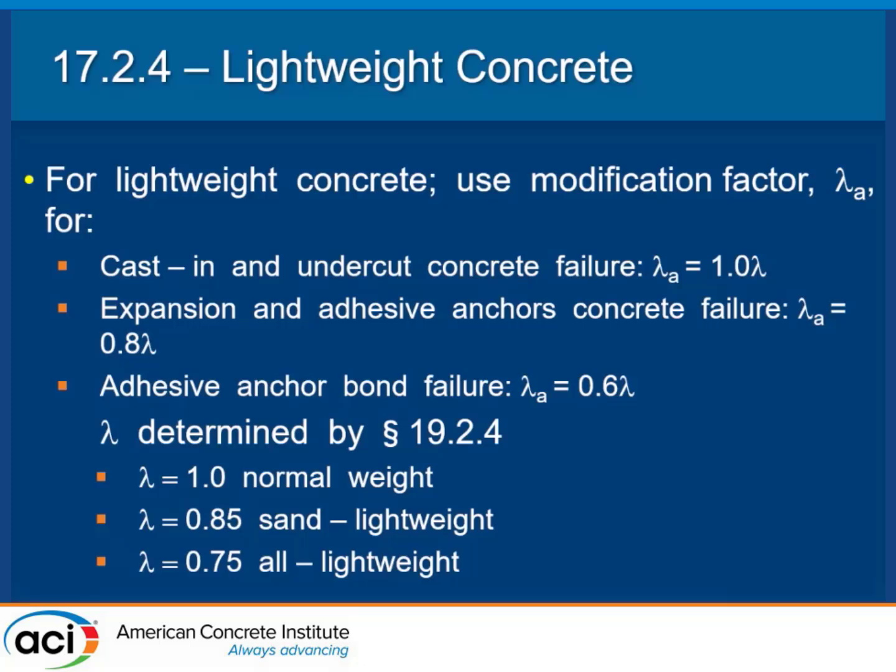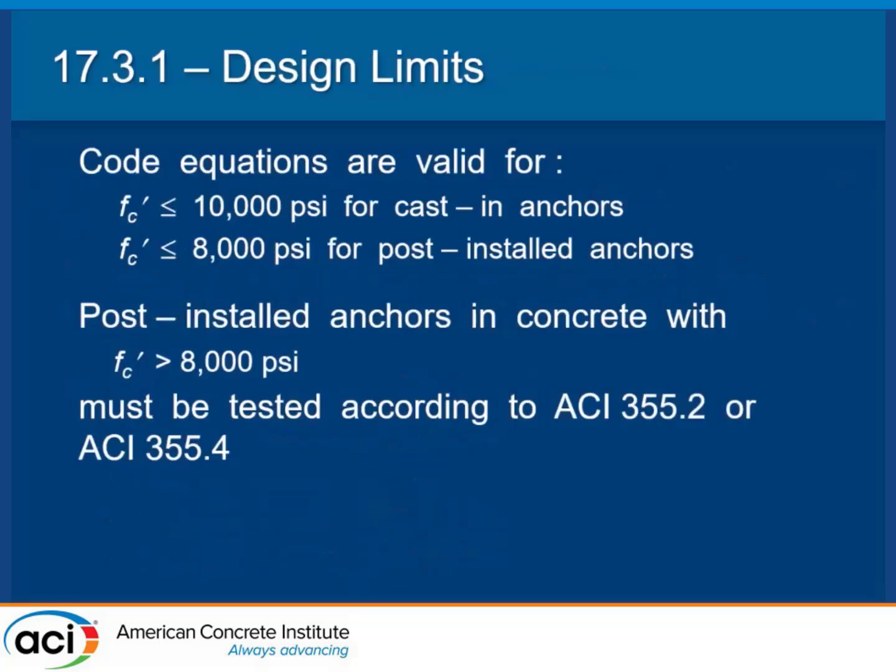Lightweight concrete has unique reduction factors for lightweight. Just know that. It's different from the ones that we use throughout the rest of the code. So whenever you see a lambda A, know that that lambda A is referring to anchorage design. That's all you really need to know there.